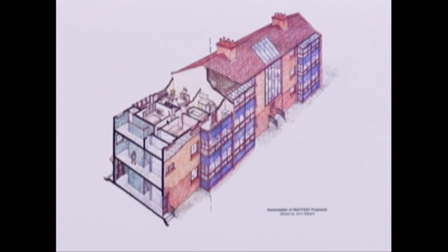So there was a large difference between the lowest consumer and the highest consumer. The lowest consumer was just below 25 kilowatt hours per metre squared per annum for space heating. The highest consumer was 215. Enormous difference, a differential factor of 8.7. So there we have it. The key things were the issue of how thermostats were set and how ventilation was regulated.